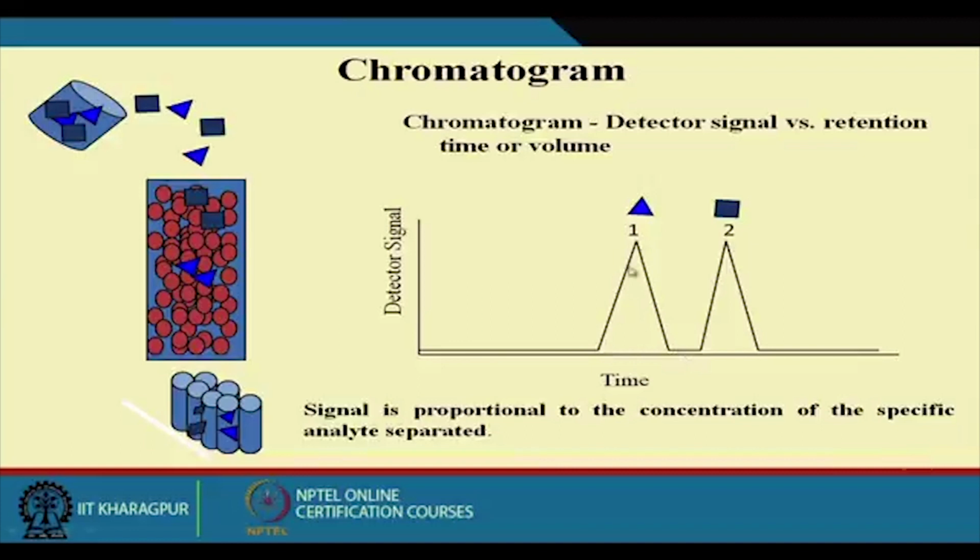So when you inject the standard, you find out what the retention time is, and what each component stands for. With respect to the standard, you have to find out which is which. Then first you have to identify what the different components present are. Then you have to inject the desired amount, because this chromatograph is used for a dual purpose, for qualitative analysis and quantitative analysis.